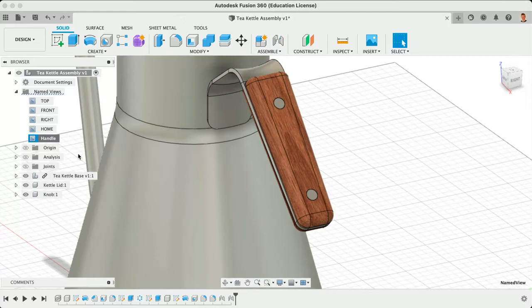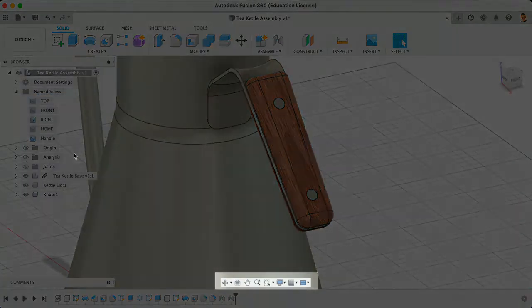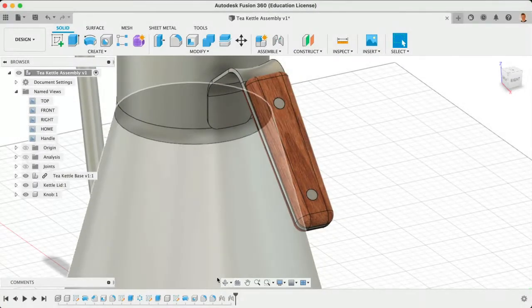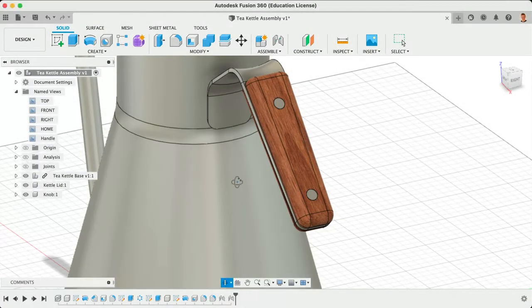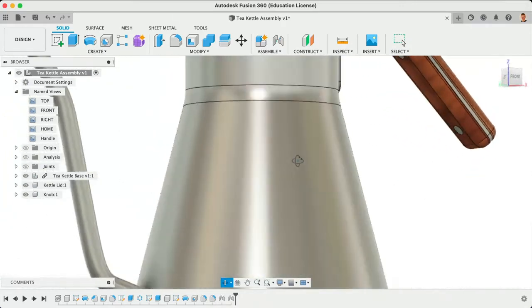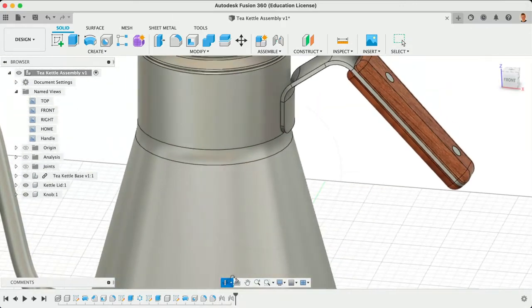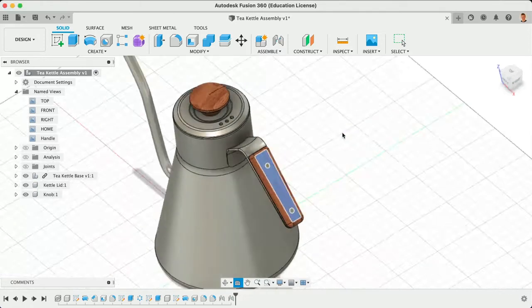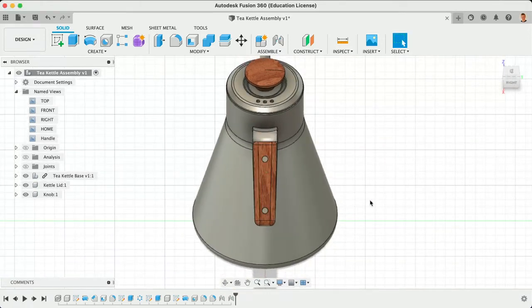The navigation bar, located at the bottom of the canvas, includes additional commands that control navigation and display settings. Constrained orbit rotates the current view around the center mark, while free orbit rotates around the X and Y axes. Look At will help you zoom in and narrow in on the desired planar face. Select the planar face and then select the Look At button, or select Look At before choosing a face.